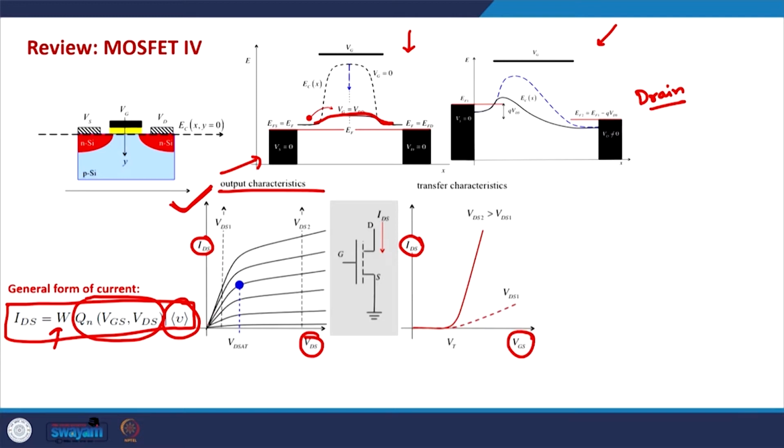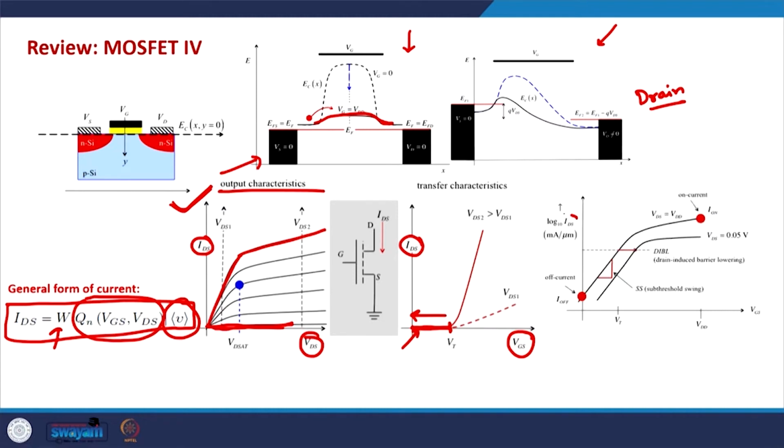The output characteristics has a linear regime, a saturation regime, and also a subthreshold regime. This subthreshold regime is more clearly present in the transfer characteristics, which is basically the IDS versus VGS relationship, and the plot for VGS less than VT is the subthreshold regime. If instead of plotting IDS versus VGS we plot the logarithmic function of IDS, this will give us a better, zoomed in picture of the current in this regime, and this is how the current will look when we have log10 IDS on the y axis as a function of VGS on the x axis.